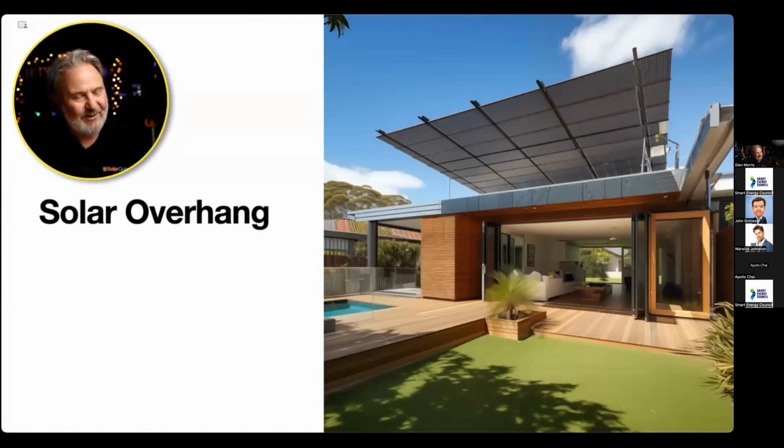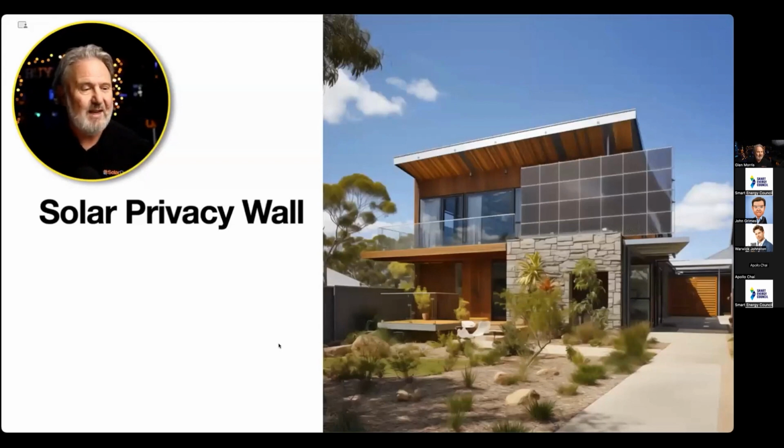Yeah, so look, can you overhang solar panels over an open area? Now, John, before the session started, said that's going to flap in the wind. Well, yes, it is. But there are engineered solutions that can be mounted in very interesting ways. This is not using standard products. You'd have to use products that have engineering for this kind of approach. So overhanging a roof is allowed, but it has to be a certified engineered design. Now, GoodWe already have a whole bunch of those for things like carports. If you think about it, some of those carports that Apollo just showed are really just floating panels with sufficiently strong struts. How about a privacy wall?